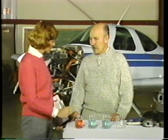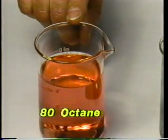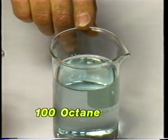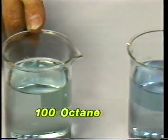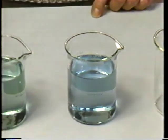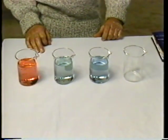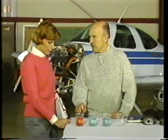And how can we tell the difference in those fuels? Well, if you notice by our samples here, the 80 octane is red, 100 octane is green, and the 100 octane low lead is blue. These colors are put in by the manufacturer when they manufacture the fuel. And this is a distinctive color for this fuel. It's a way of identifying it.